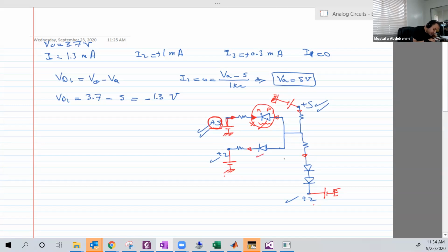But these 3 diodes here are connected to lower voltage batteries, so they can accept a charge from higher battery voltages like this one. Because if they are accepting a charge right now, the current will flow in that way, and the diodes can allow currents flowing in that way.